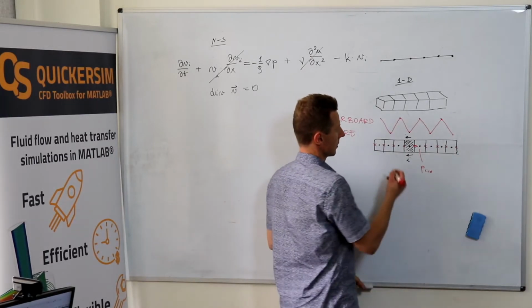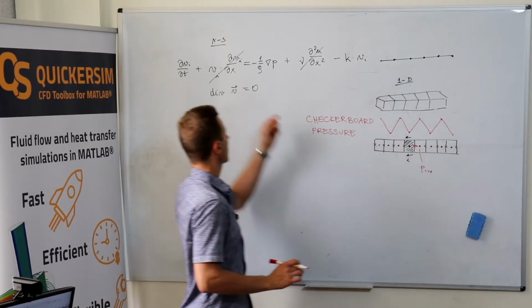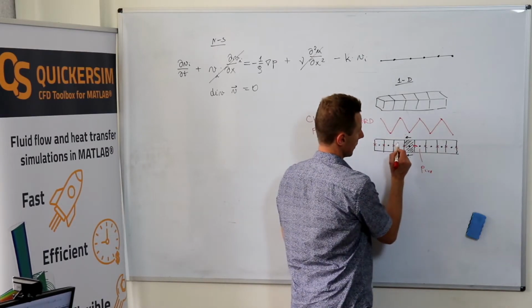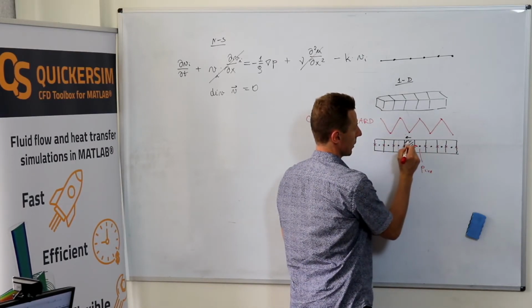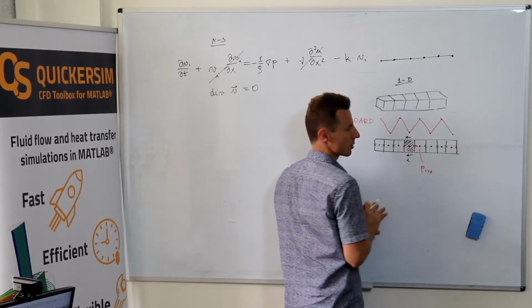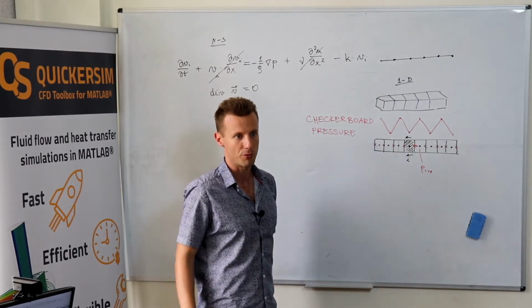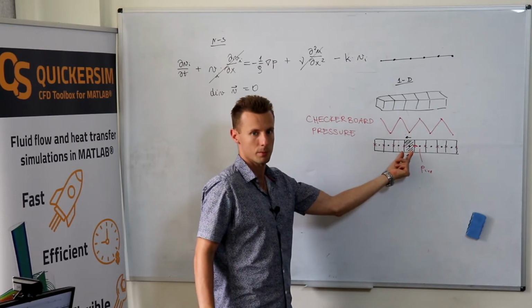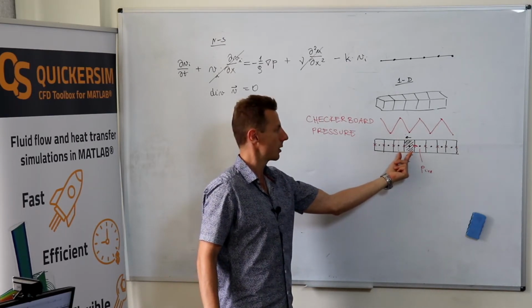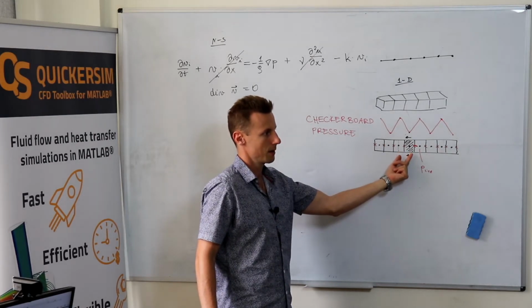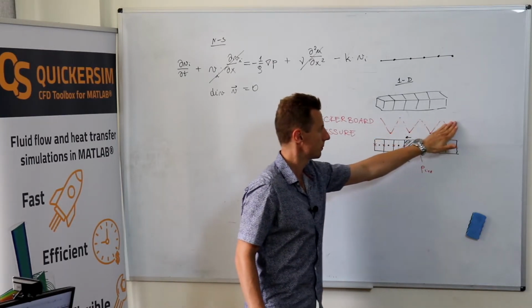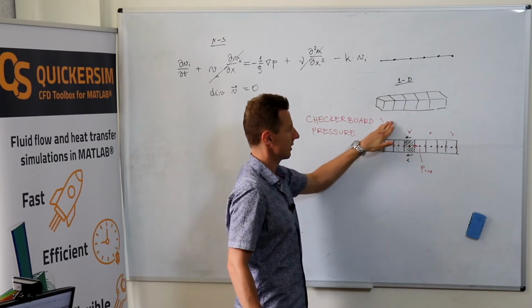Then if you want to discretize the Navier-Stokes equation, you're drawing such finite volumes for velocity discretization, and then pressure variables are directly accessible at the interfaces of these finite volumes, and you get rid of this problem. So it's already properly defined.